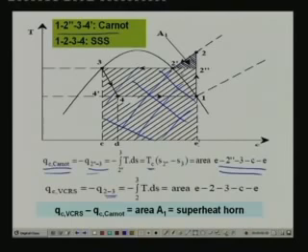So you find that the difference between the heat rejection of a vapor compression cycle and the Carnot cycle is nothing but this area 2 dash 2 double dash, or area A1. Okay, and this area is known as superheat horn. Okay, and this is coming because of the fact that we are replacing the isothermal heat rejection of the Carnot cycle by an isobaric heat rejection process.